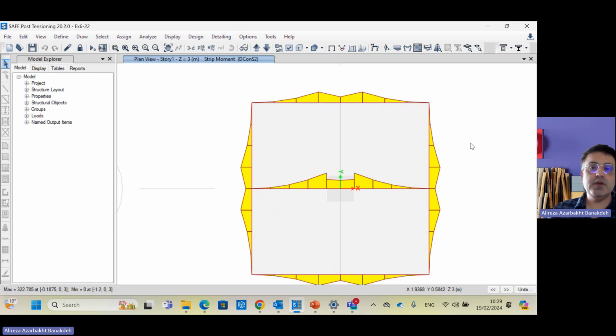However, first of all, we are accounting for the flexibility of the pad foundation here. On the other hand, the hand calculation assumes that the pad foundation is a rigid one. In addition, we are modeling the column in the middle, which suppresses the moment distribution at the middle, which should be maximum. For example, this is the distribution of moment in this line.